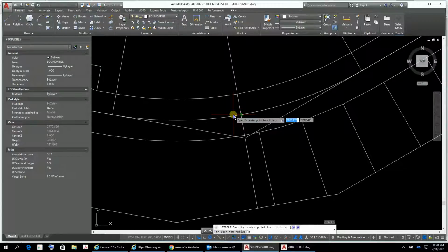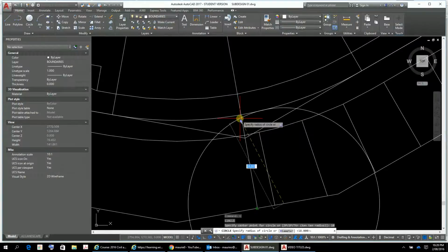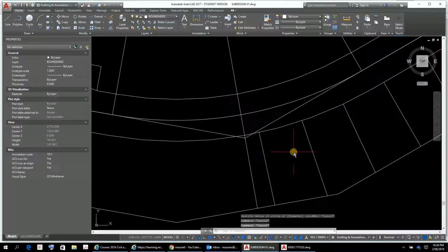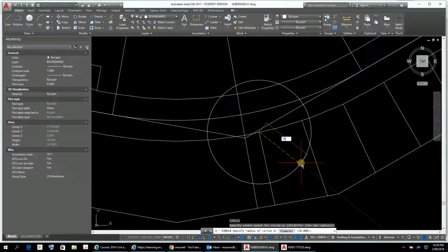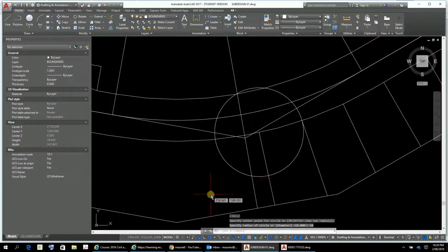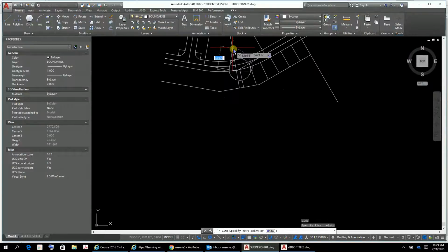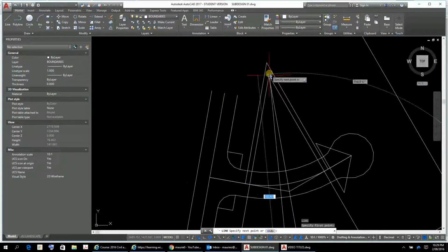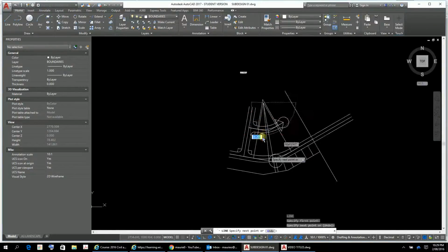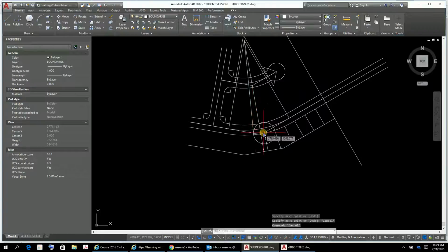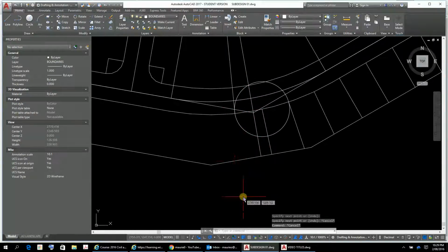So that's C, enter, circle, enter, 18. Oops, that's a bit premature there. C for circle, enter. Now let's select here, and let's do 18, okay, and draw a line from here, again, through to the center of the arc, or the circle that's part of, like so, okay, and then I'm going to extend that.